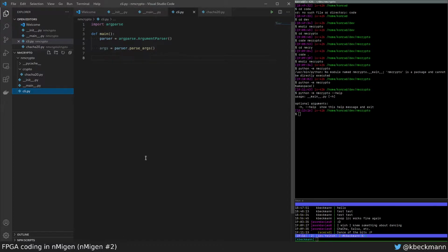So I'm thinking of both having simulation and also synthesis for different targets, but having fake targets. So for example, an ECP5 FPGA, but one that doesn't have to exist, and just set up some fake pins just to be able to test the tool chain and see what kind of LUTs and performance we get. I think that would make sense.